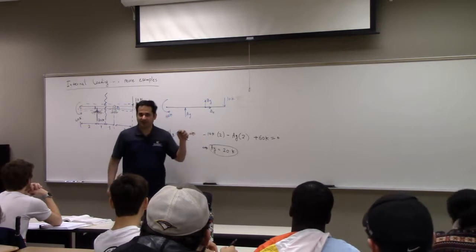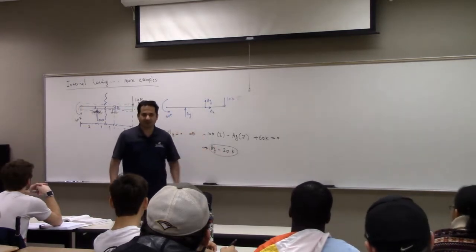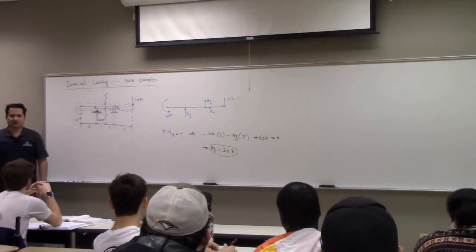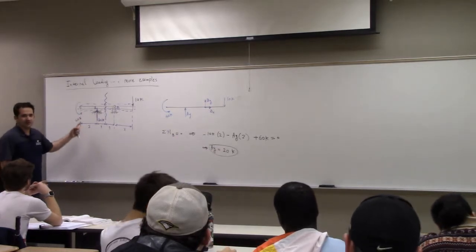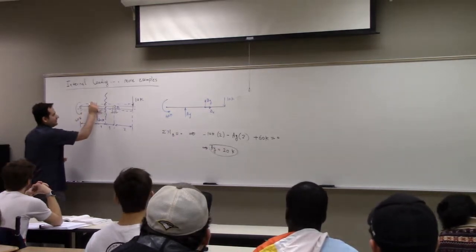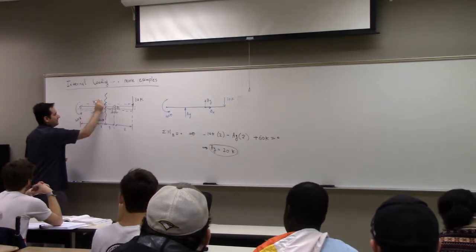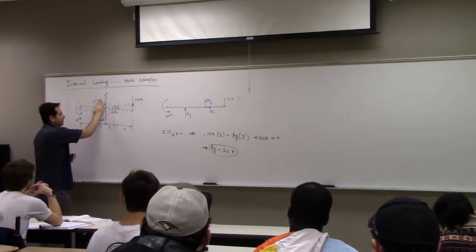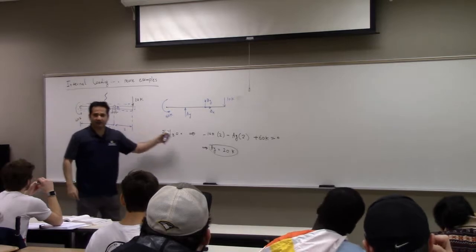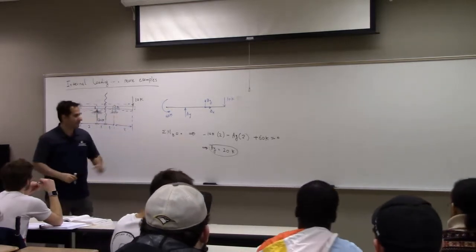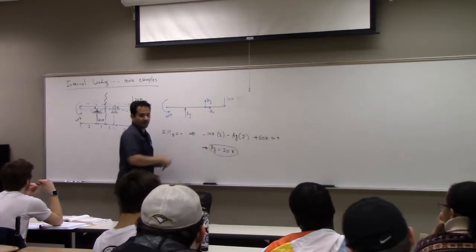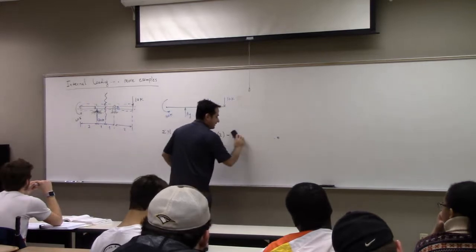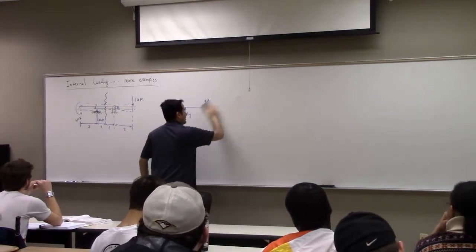Now imagine if I do the same thing and I get negative 20K. Remember the last step was verification. Is it possible that I get negative 20K with this configuration? Then you say, well, it's either the teacher designed the wrong problem, sometimes it happens. So in that case, you have to do a double slider, like that, so you can have both positive and negative. Or you did wrong computation, so you have to go back to the FBD and see what you have done wrong. Usually the problem is either the moment computation or the FBD is wrong, right? So I have this. Now I have my 20K, so I can get rid of this preliminary calculation.